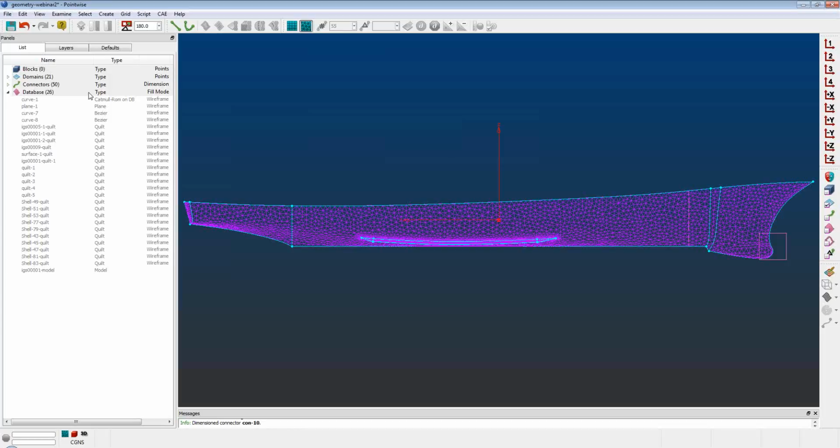Now that process, you can imagine if you have multiple cases, ultimately you have to go through the cleanup process at some point. You have to do it on the CAD level or the mesh level. So if you're just going to do a one-off, you can just do it on the mesh level and be done with it. Now if you're going to use that geometry over and over in subsequent analysis, it's probably a benefit to clean things up on the geometry level, save that geometry cleaned up, and then every time you return to it, it's already fixed and it's watertight, and you just go ahead and mesh it.